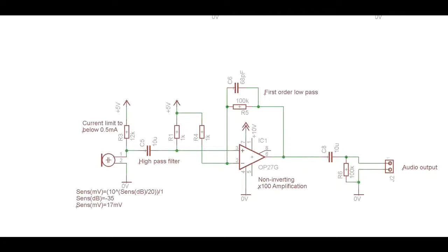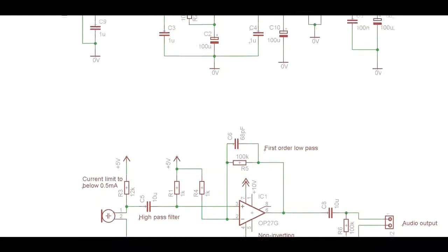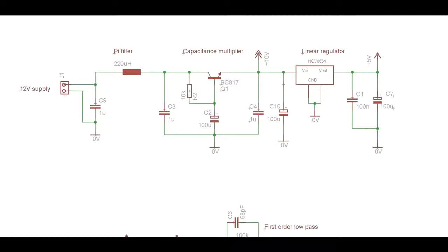The choice of amplifier will influence the power supply. For this IC, I have a common mode input voltage range of 4 volts away from the supply lines. And I want about 2 volts of output voltage swing, so I need to supply the amplifier with a minimum of 10 volts, after filtration, from a 5 volt USB. This will be fun. Okay, I need a voltage reference now to have my circuit centered around something, and 10 divided by 2 is a very common 5 volt, so a linear regulator will give me my reference. I will use this supply network also for the microphone.